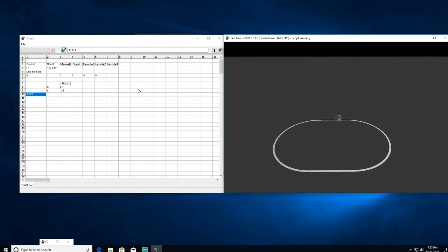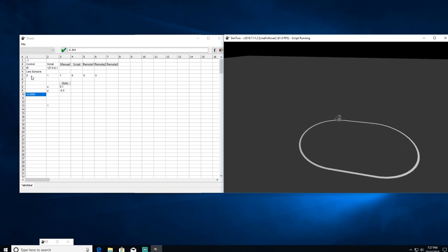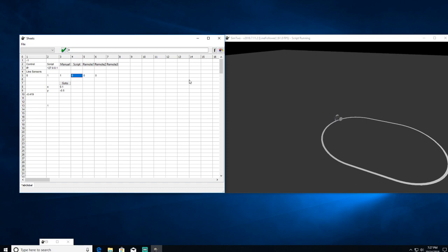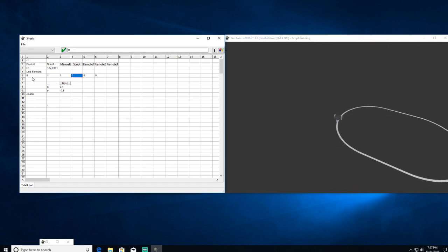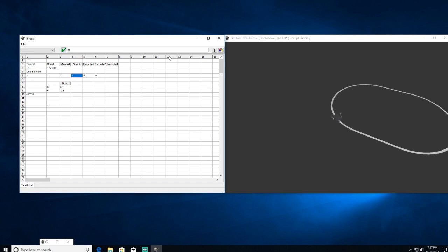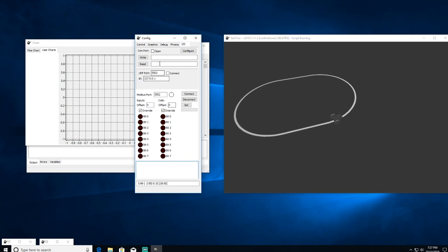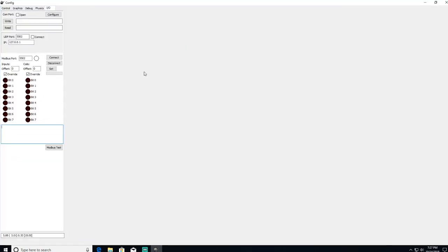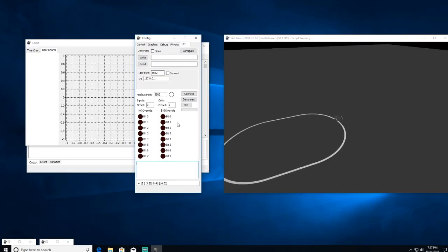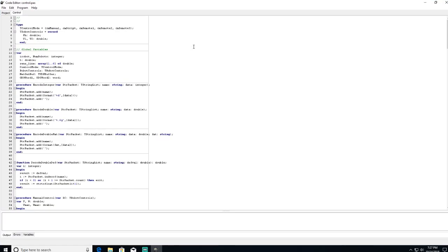So this is similar to Excel. You see the variable values, you can see the line sensor simulation values, and based on that we can determine what kind of gain we need to improve, what kind of code we need to improve. So if you're looking at the code itself, the next step is the code editor. This is in Pascal, and has your subroutines based on the number of robots you have. You can have more than one robot, and you can choose how many line sensors you have in each robot. You can have up to 6.